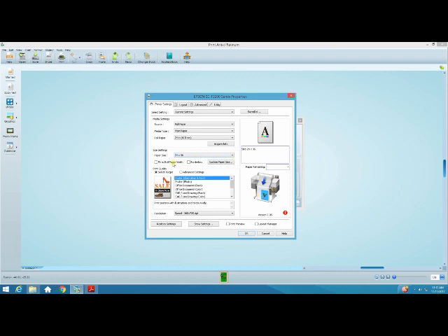Now, here's what happens. Fit the roll paper width. If you are working with a 24-inch roll, 36-inch roll, 42-inch roll, it makes absolutely no difference depending on the printer that you're using, and you are creating in that width, that's what you're going to select. So for instance, we're going to hit fit the roll width because we're going to work with a 24-inch roll, and you'll notice that this went all the way across. Okay, if we unselect it, see how it changes? All right, so now we've gone all the way across.